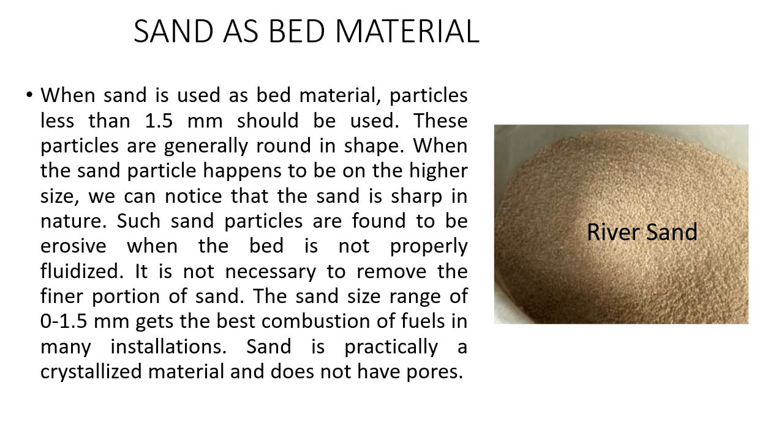When you use sand as the bed material, particles less than 1.5 mm should be used. These particles are generally round in shape. When the sand particle happens to be on the higher size, we can notice that the sand is sharp in nature. Such sand particles are found to be erosive when the bed is not properly fluidized.